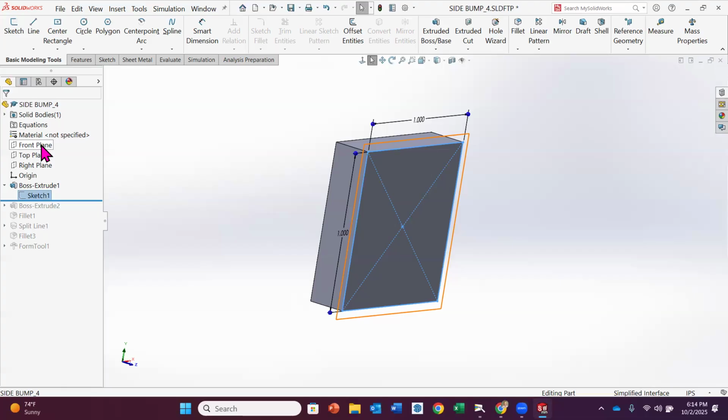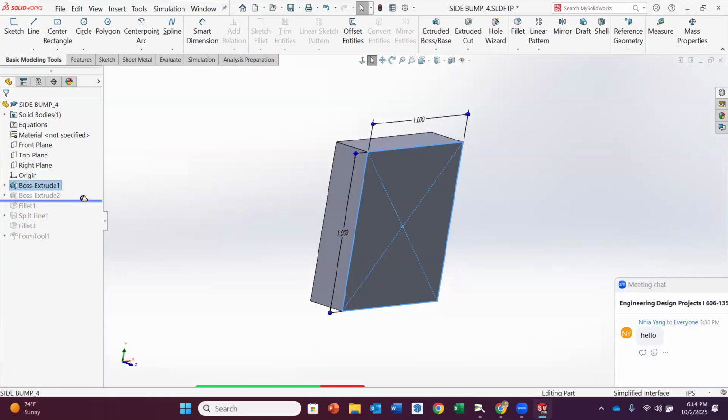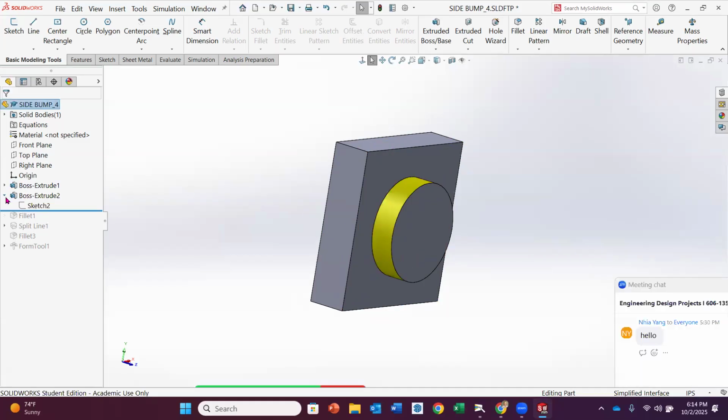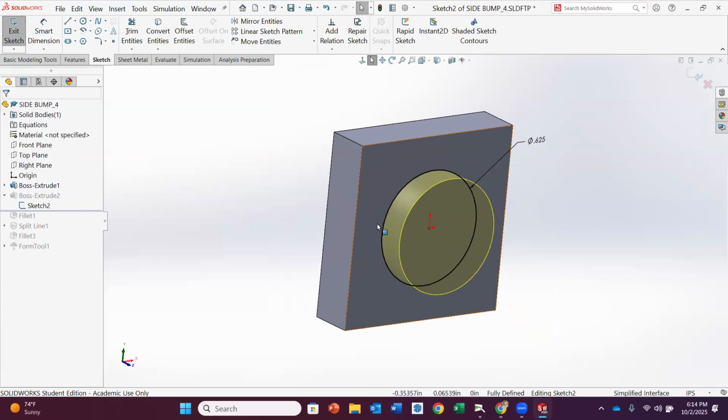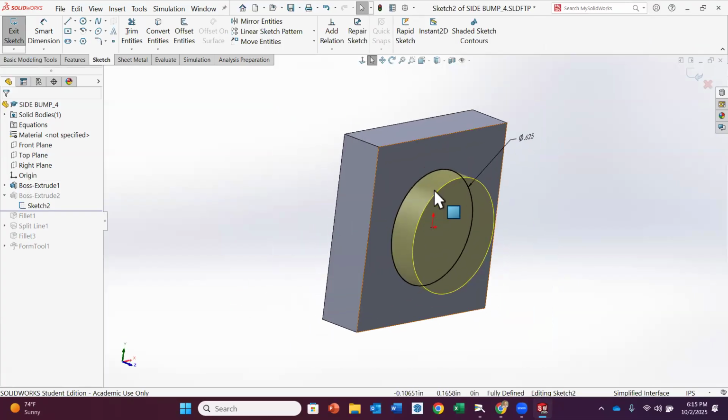So always flip that direction so that we're going to be on the front surface when we're creating our form, okay? This can just be a generic rectangle that's just going to be larger than whatever the form shape is that you're creating, okay? Now I'm going to go down and create my sketch for whatever my form is going to be, okay? Now, notice that I went on that front face or that front plane. Okay, so here's my front plane and I came forward.